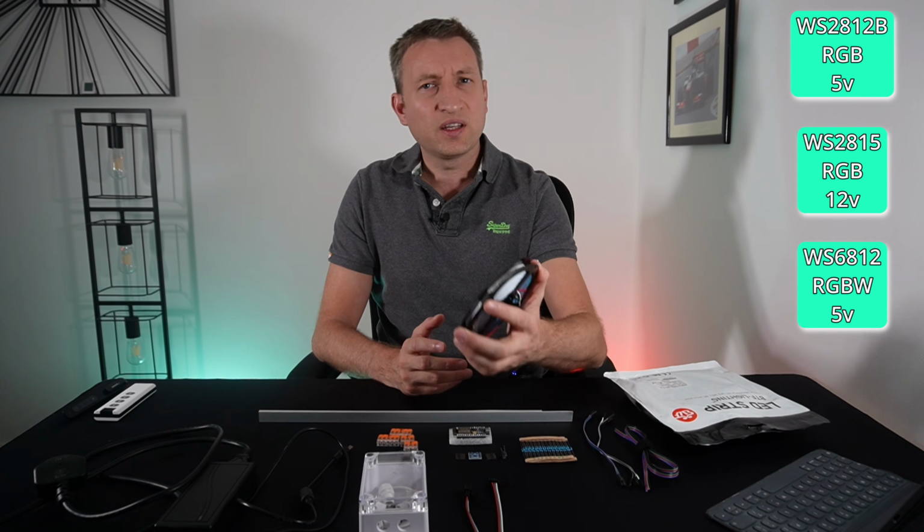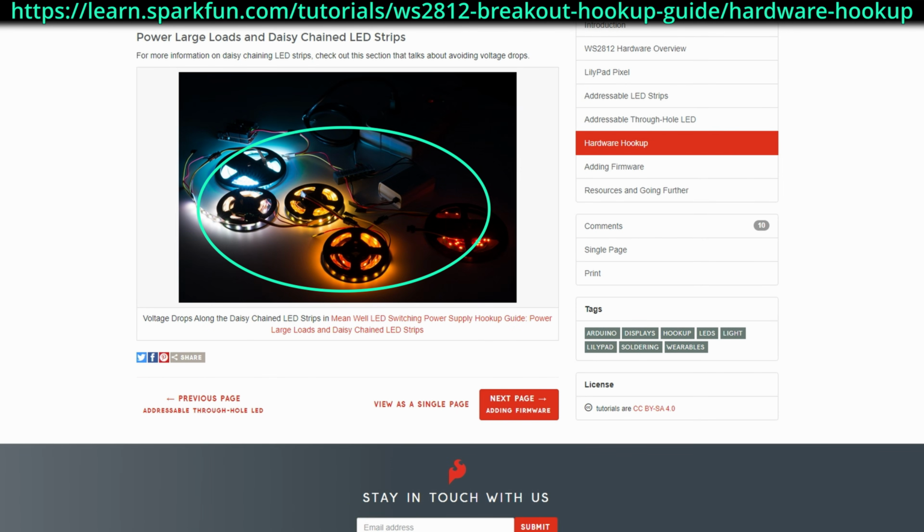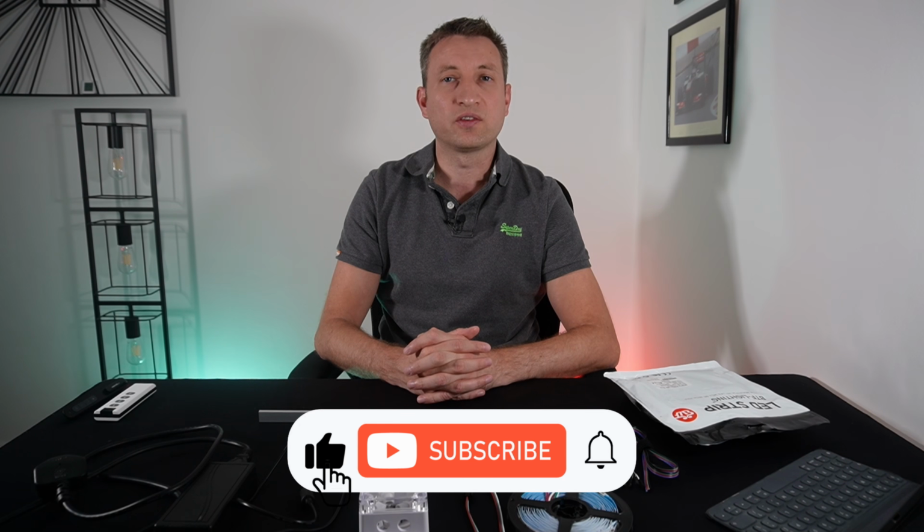And then you've got the SK6812s, which runs at 5 volts like these, but also has a white channel, which can be really useful because the white on these is not a pure white. So if you really want a pure white, then you'd go for those instead. One of the problems with these LED light strips is the voltage drop and high currents. And with the voltage drop, you can get an inconsistent light across the light strip, and also there's increased risk of fire with higher currents as well. So this is why the WS2815s can be a good option, because they run at 12 volts instead.